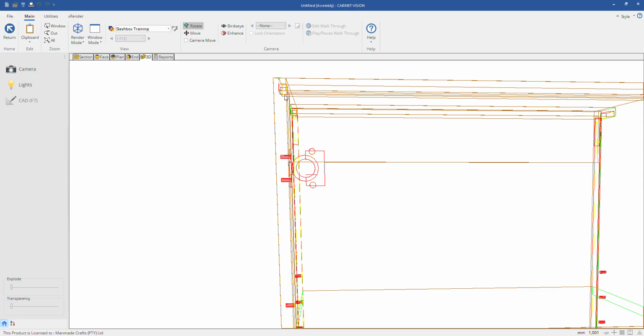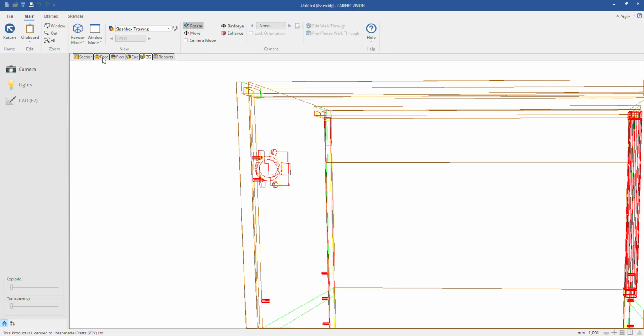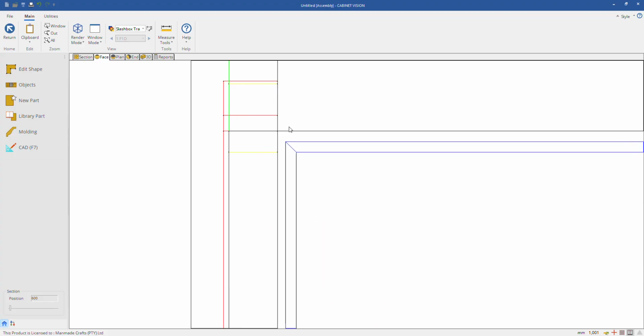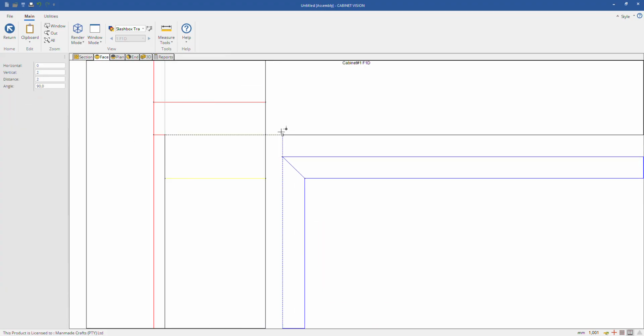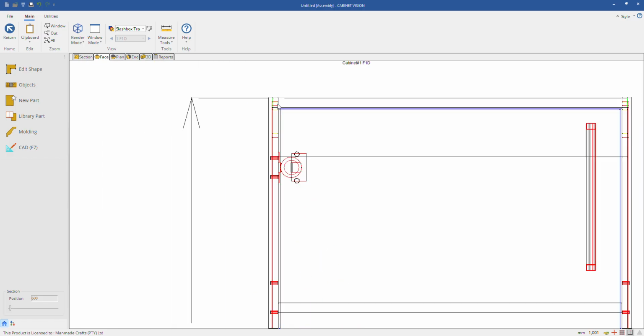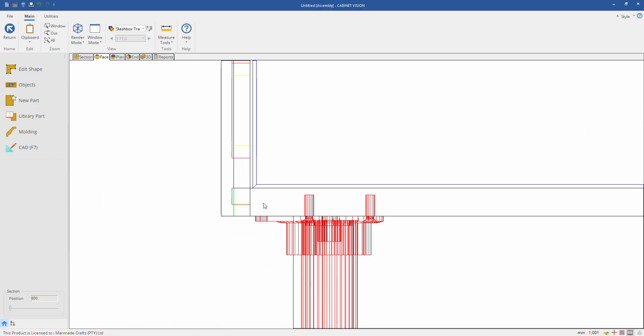The correct reveals. So it uses the same reveals that we had on our overlay versus the inset. What's that, 1.5? 2 meters, this is on my construction method, and 1.5. Yeah. But that's why if your construction method is set correctly, then your reveals there will be correct. And in the bottom reveal, you see what it's done in the bottom. It'll be true as well.